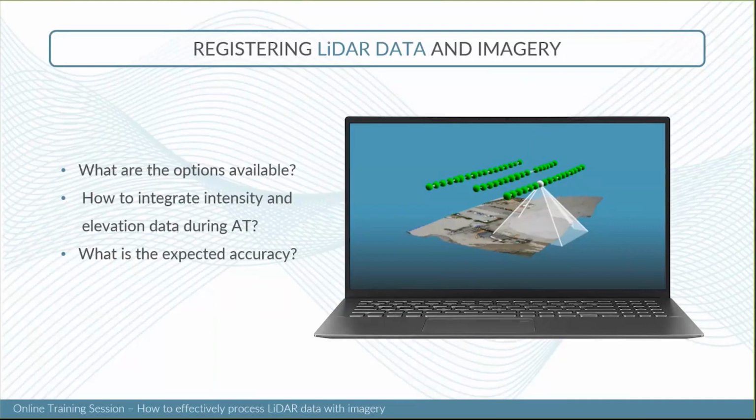This workflow also applies for people who are flying UAV missions over and over again and want to use previous mission results as ground reference for their next project. So you make sure that your projects are stitched on your previous project, so all your sources have a good absolute accuracy over all your projects together.